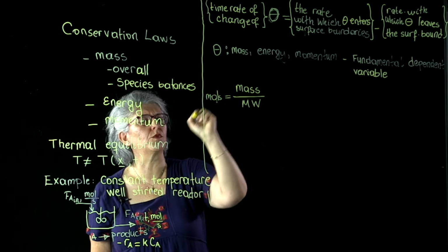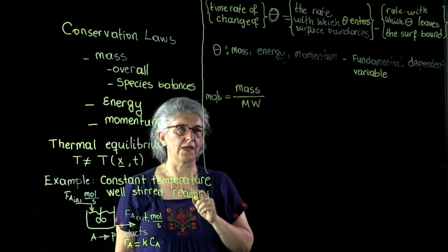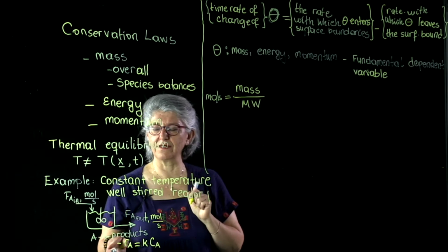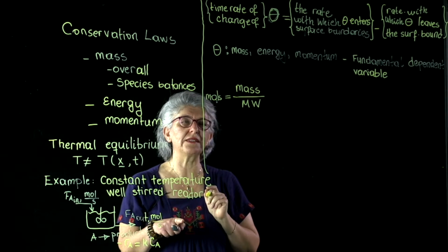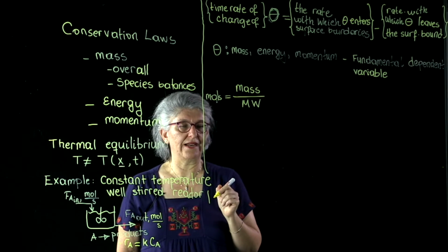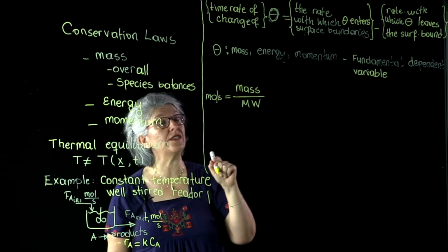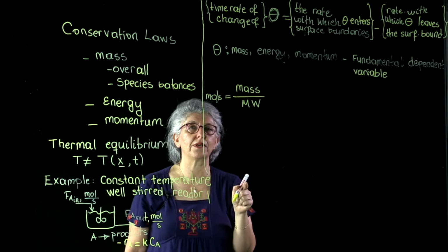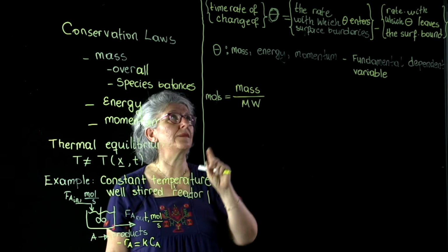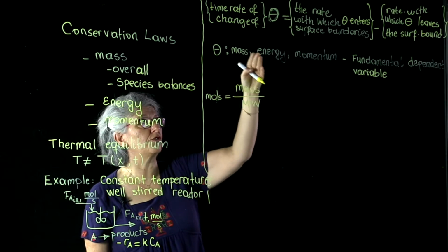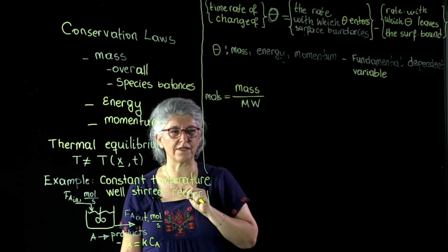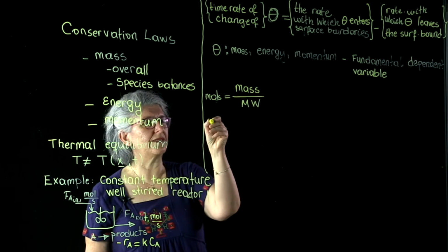All right, you get the moles. But the nature of the problem is that because of the reactions, moles can be generated and consumed. And now, when we write a mole balance, it is no longer a conservation equation, but it is a balance equation. So we still have the same concept, time rate of change of, but this is no longer a conserved quantity. So we are going to write the mole balance.